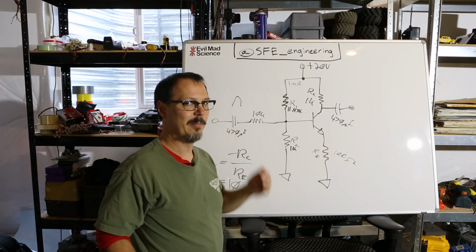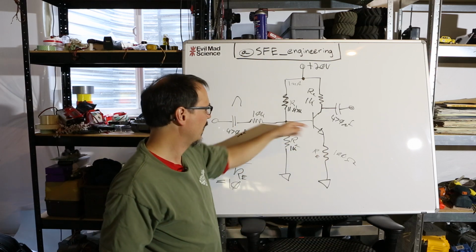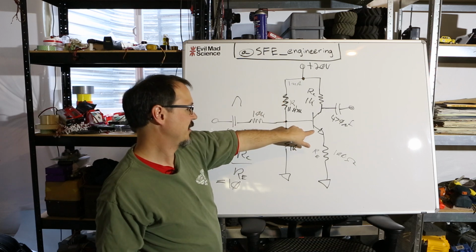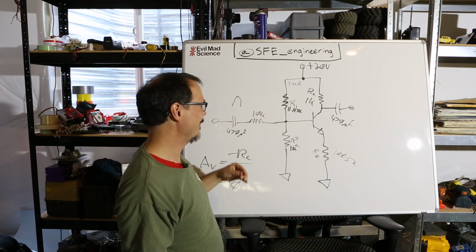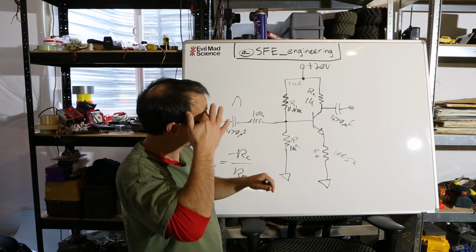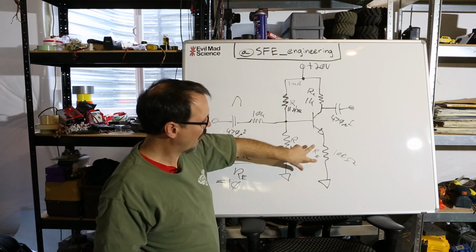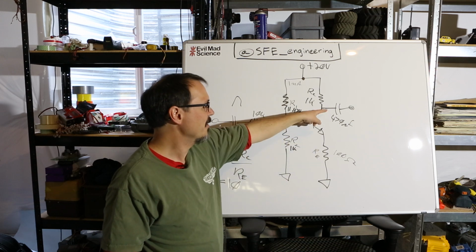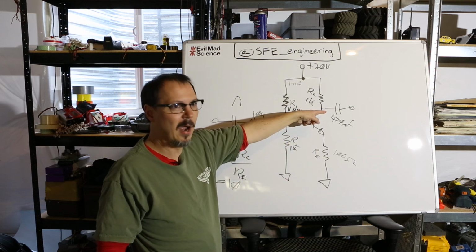Now that's negative feedback, because as that voltage comes up, this voltage is holding steady because of the divider, right? So you're effectively turning this guy off. That'll take away from your gain. You're shutting off the transistor. Not only that, but you're always going to have some of your voltage across that guy, and you're never going to get the full swing out of your output.